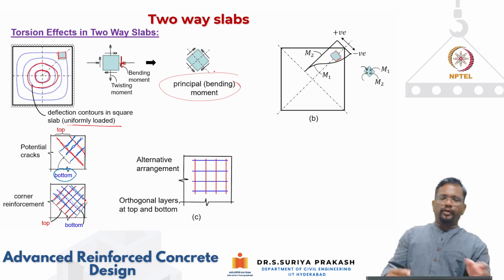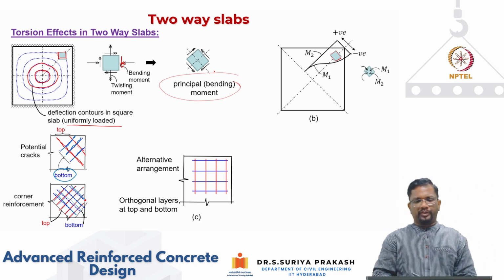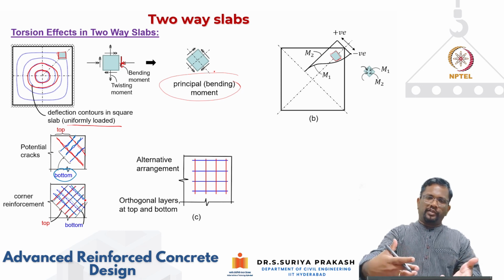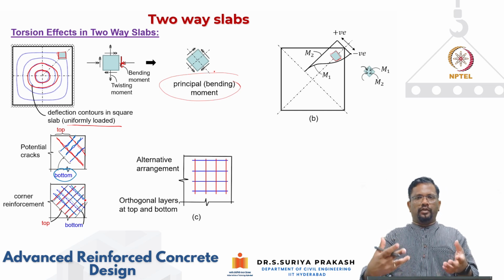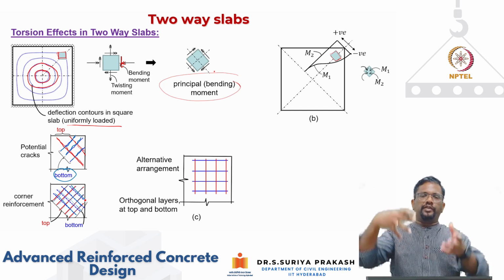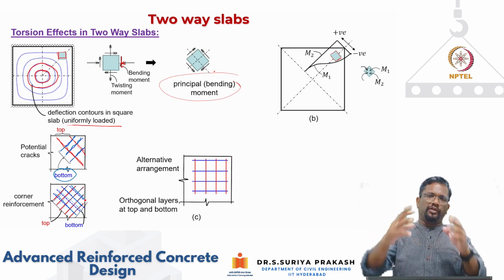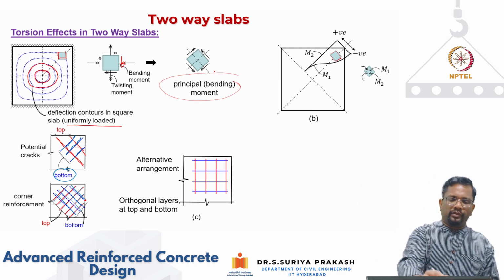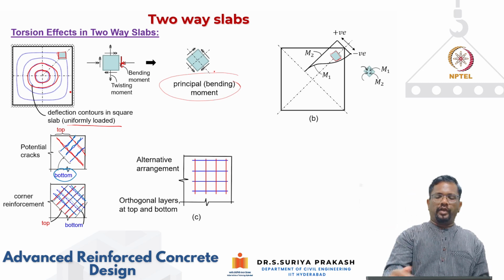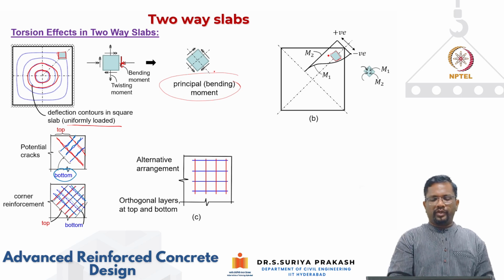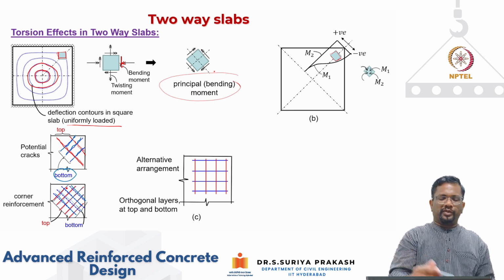So in this way, we put some corner reinforcement, especially when these slab panels are prevented from lifting up, this cracking will happen. So always, if you are preventing some rotations and deformation, you develop reactions, right? So if this panel is restrained from lifting up, you will develop these principal moments and this crack. So that's why in the corners of the slabs, ideally, we need to put reinforcement at an angle, but it is very difficult to execute it in the field.